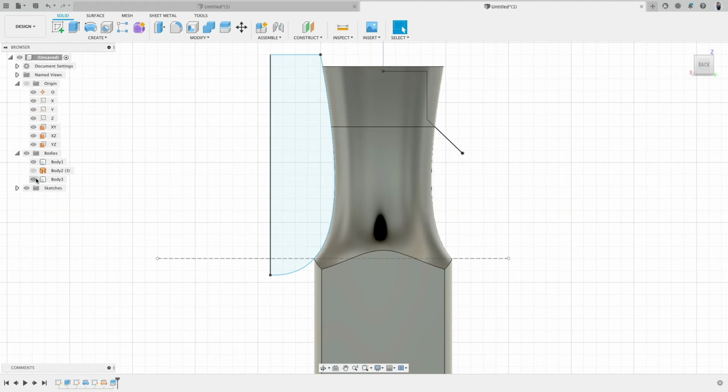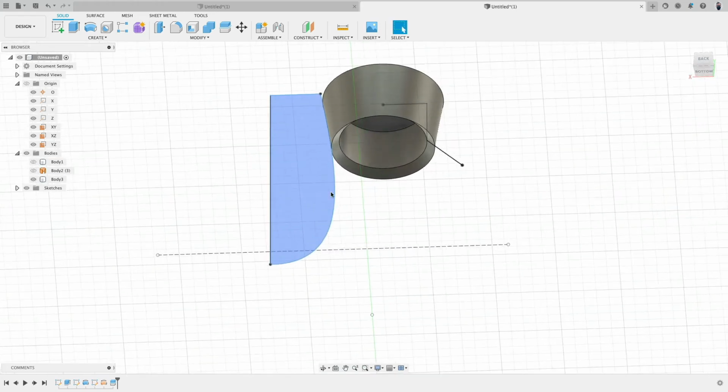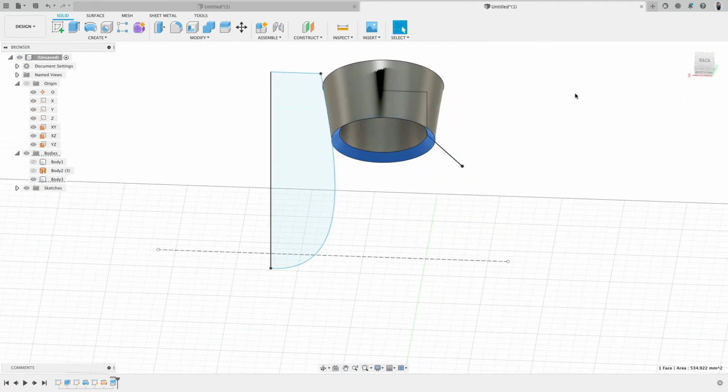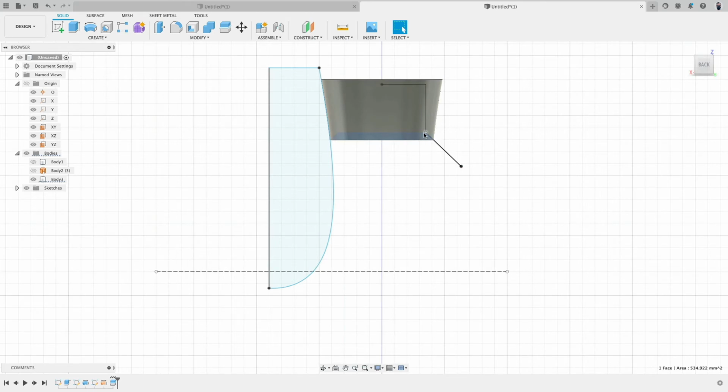Okay. Since we're splitting everything, let's continue splitting more because while the bottle is good, the cap sits perfectly on it and has an angled surface there. That's not good. This needs to be trimmed and I need to have 2 millimeters of tolerance for threading.